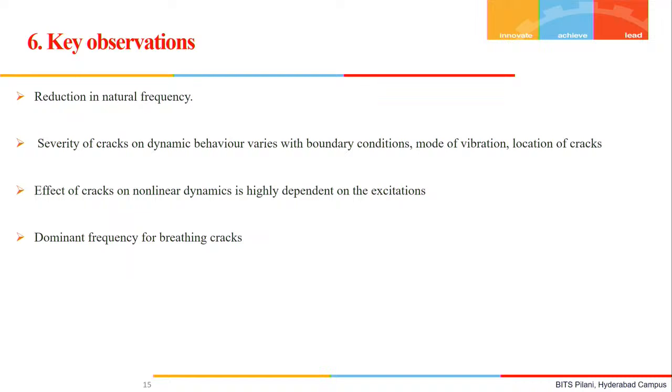We have also seen that the same structure, when it is excited with a single frequency excitation, gave a different type of response. Basically, the dominance of a particular mode was happening in some particular cases for the intact beam, and this completely changed when we saw two frequency excitation or multi frequency excitation. When we excited with a different excitation pattern, the crack affects the different modes differently. That is what we have seen also.